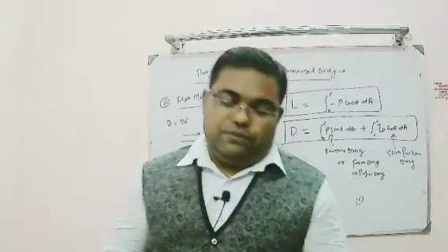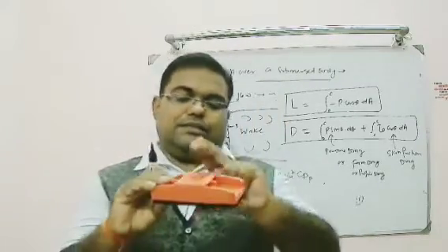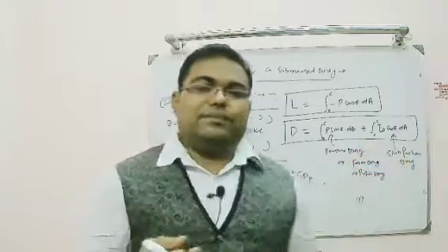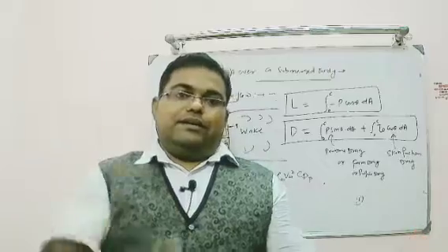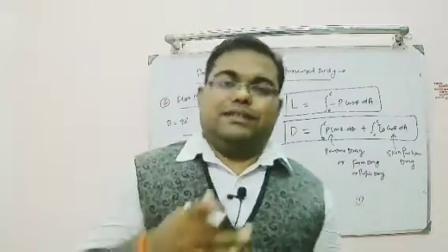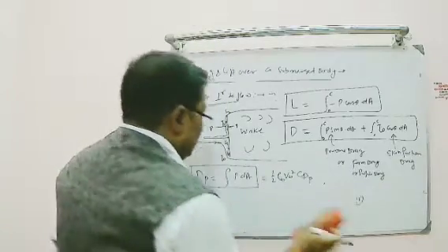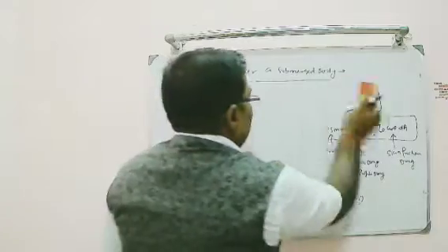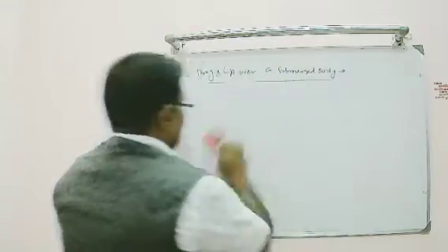So we have seen that if the thickness is less, I will have lesser drag, and only skin friction drag will be present. If the thickness is bigger, I will have pressure drag, and the pressure drag contribution is more compared to the skin friction drag. Now I am going to compare three bodies in a similar way, to see which case gives which kind of drag.